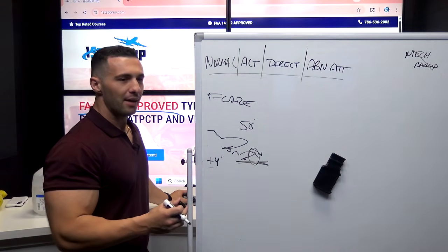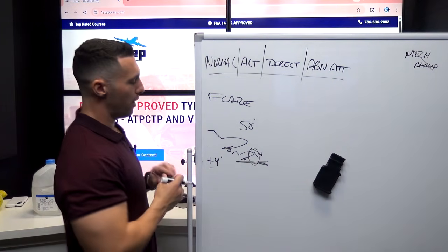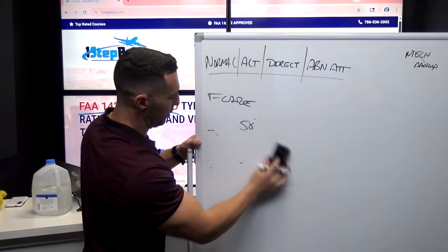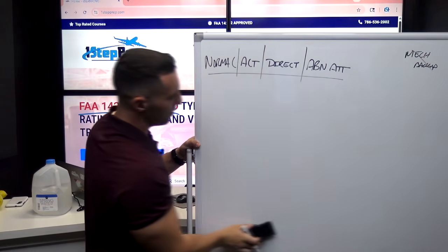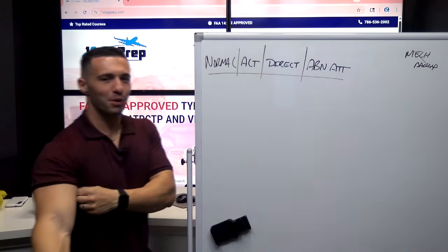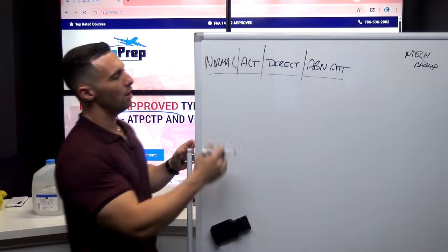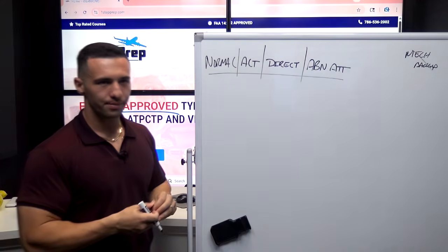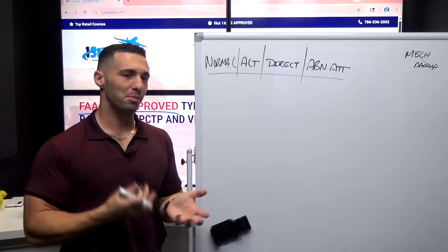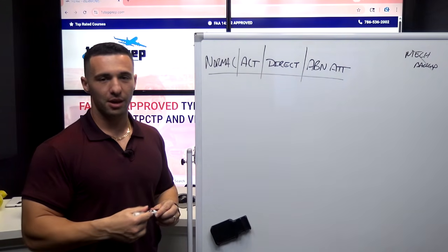Okay, so that is ground, flight, and flare mode in normal law. So now we're going to degrade in laws, left to right, progressively getting worse and worse here. So from normal law, we go to alternate law, and basically the way that we go to alternate law is by losing a system plus a redundancy. That's kind of the nutshell answer to this.